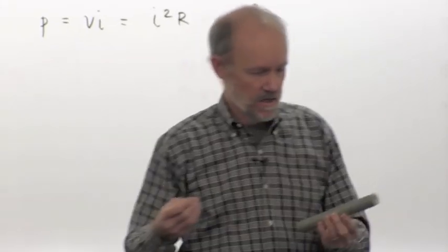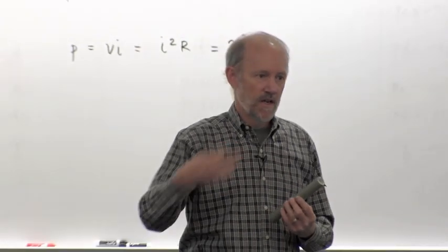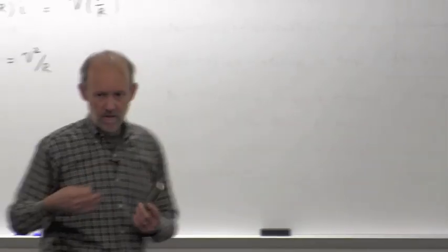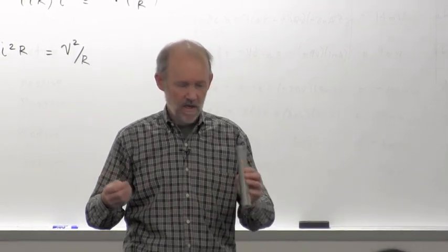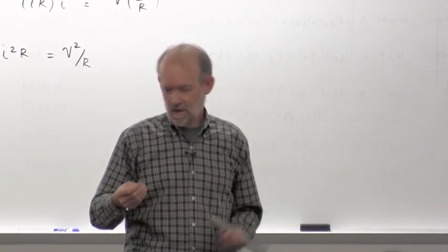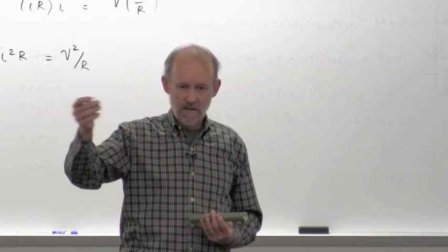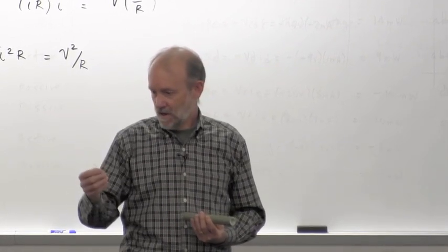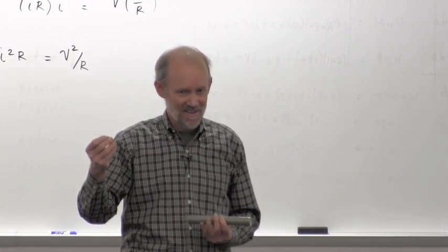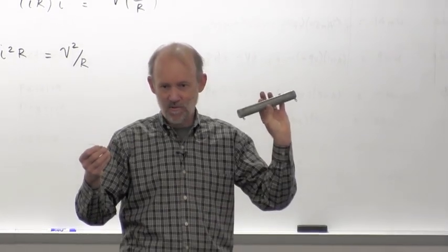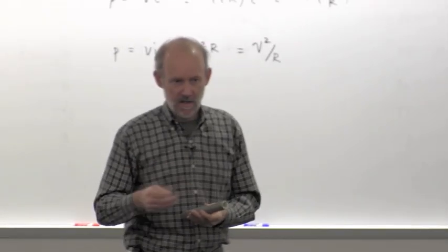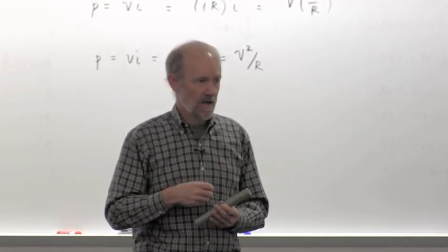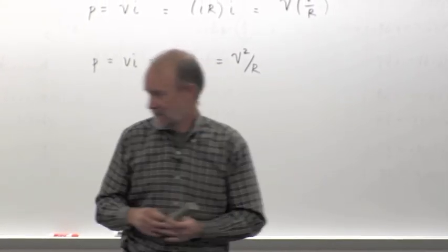So I just want to emphasize ratings are extremely important if, as an engineer, you're trying to specify a design and you send your design down to have somebody build it. If you intended to have this in the circuit and you didn't give any specifications and they put this in, you can imagine this will probably melt under the heat that this one was supposed to be able to absorb. So again, pay attention to ratings. That's another important specification other than just the nominal resistance.